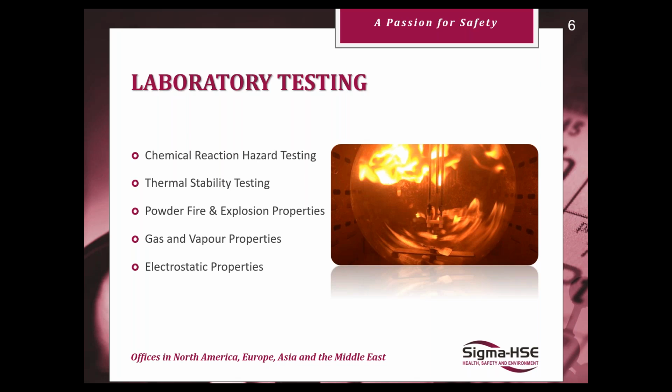And then there are the powder or dust fire and explosion properties: severity, sensitivity, dust combustibility, gas and vapor properties, also flammability limits. We've got a really nice picture there of an upper explosible limit test of a vapor system with a nice bright orange flame. And we also do some electrostatic properties testing to tie into primarily the powder and dust testing as well.